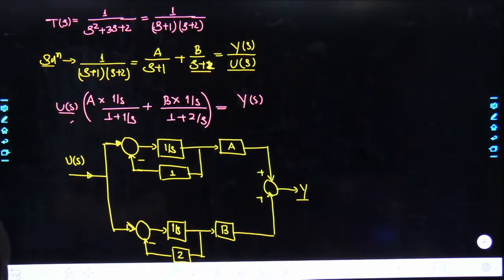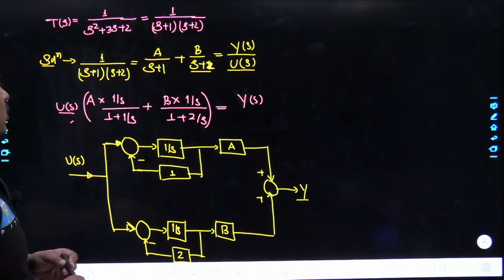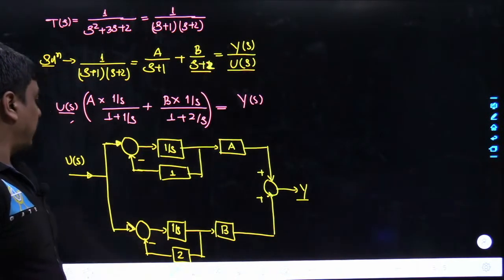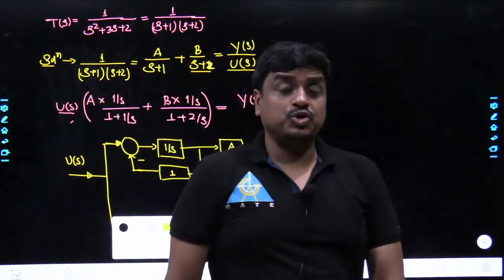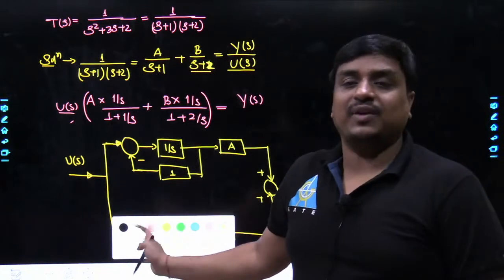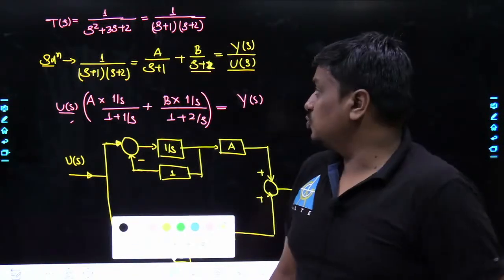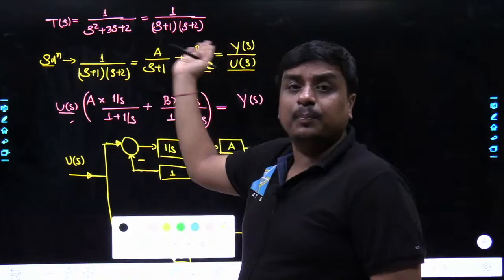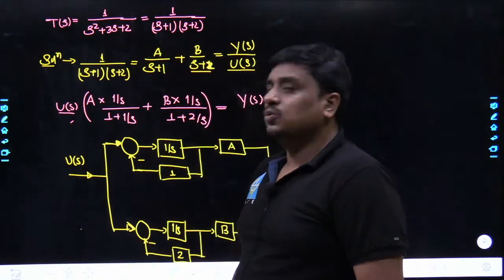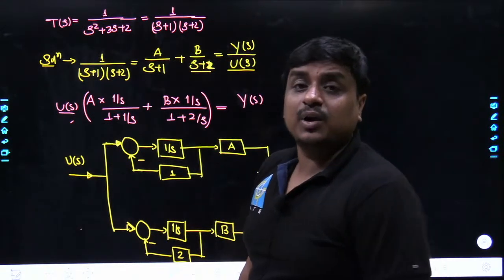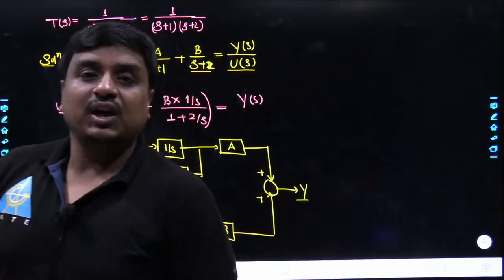Till this point nobody should have any doubt as such. Agreed? Now again the next thing comes in mind, how many variables we are going to choose to smash this problem in terms of SSM? Two variables we are going to choose. Why? The number of poles involved with the system is 2, the order of the system is 2, that's more than adequate to indicate the number of state variables we will be choosing is 2.